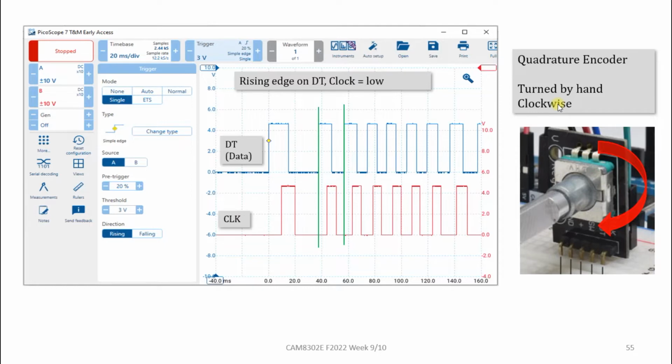And that's one of the features that's important with a rotary encoder, is you can determine the direction that you're turning that control knob, clockwise or counterclockwise. And we're going to be able to tell how many degrees we've turned it. Okay, this particular rotary encoder has 20 pulses every 360 degrees. So that's 18 degrees per pulse.